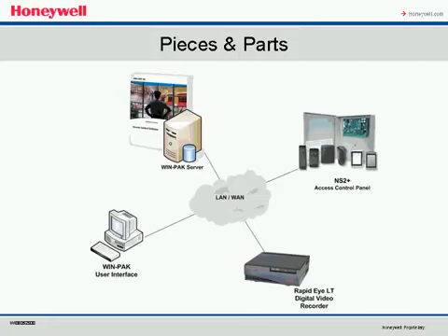Okay, I get asked that a lot if I'm out there selling. If you do need to tie in the integration, where when this event happens, I want the PTZ to zoom over to this location, that can be pre-programmed through the DVR. And for right now, until it's coded into the software, we can use an input or an output point to generate that. Okay, so we could take a relay out of the access panel, take it to the DVR. Right, that's how we accomplish that.